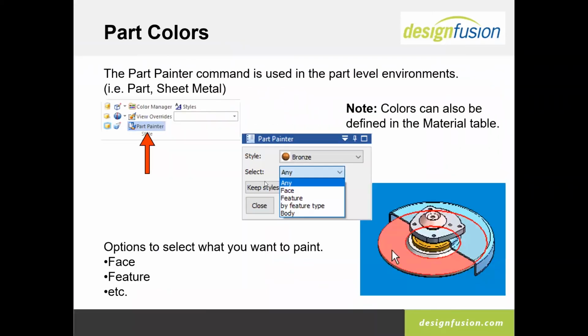So there's the part color. So if you want to paint parts, and it's a good idea to have different colors so you can distinguish them. An entirely gray assembly is hard sometimes to distinguish the separate parts. And in case you're wondering, yes, you can use things like wood grains, rock grains, granite images, this type of stuff. That will go in your texture tab on that color, the face style dialog.